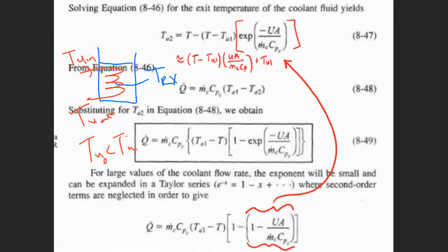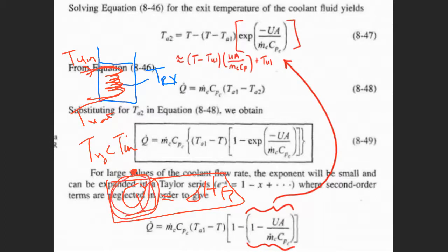When we consider heat transfer, we've got the energy balance that says Q must be equal to delta H of my flowing streams. But now when I start designing the heat transfer devices, I need to compensate for the fact that this rate at which I want to remove heat must also be equal to how fast can I take it away. So this is what I want, and now I need to design my heat transfer equipment to make sure that this actually happens.